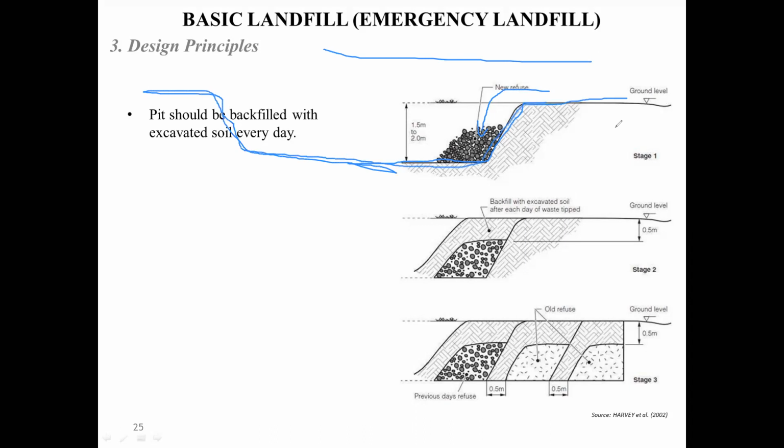This is emergency landfill, basically when you don't have a proper monitoring system, or let us say there is some part which is going to be used, or there are some issues which have taken place. So they're going to be taking emergency landfill or basic landfill. In that case, whatever landfill they are going to be taking, the pit should be backfilled with the excavated soil on a day-to-day basis.